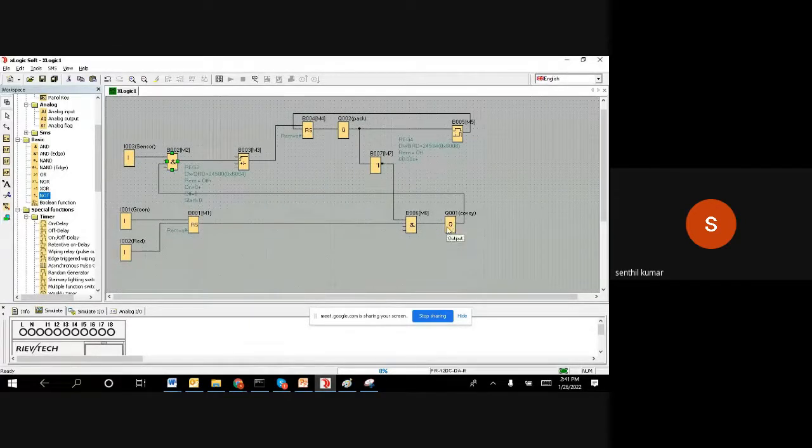So when the conveyor is running and if the sensor is coming, then we start counting it actually. So 1, 2, 3, 4, 5. Once the 5 comes, then we are setting it. Once we are setting it, the packing motor will start. So remember, when the packing motor is starting, we have to immediately stop the conveyor motor because we don't want the single bottle falling on it. So once it is on, this NOT gate will become off. When it becomes off, then one leg is on, other one is off, so you get off. So this will go off.